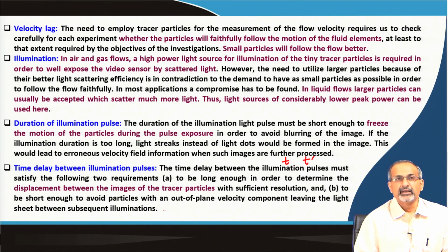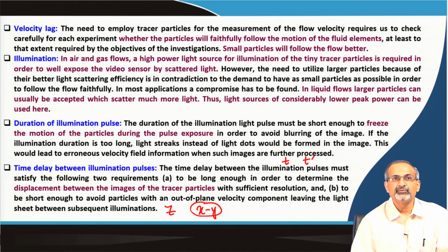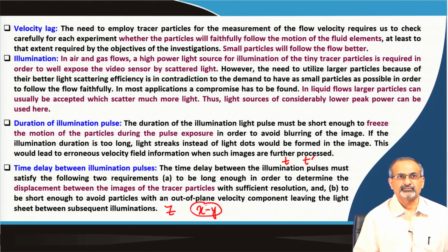That means if you have a little bit of z velocity component, then the particles which are ideally supposed to follow the xy plane, the plane in which the light sheet exists, they would leave that plane altogether if you expose for too long, or rather if you have too much of a time delay between the illumination pulses.